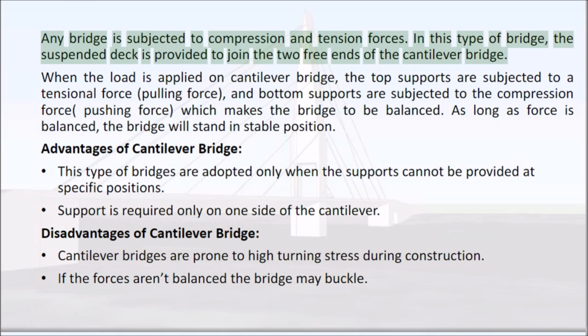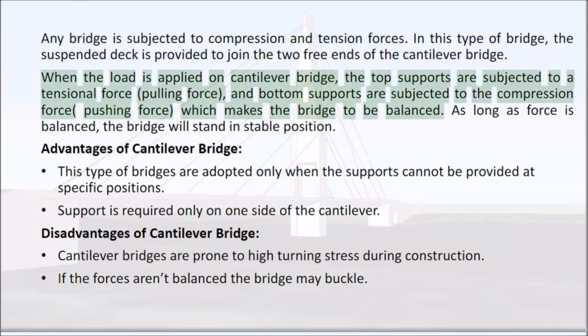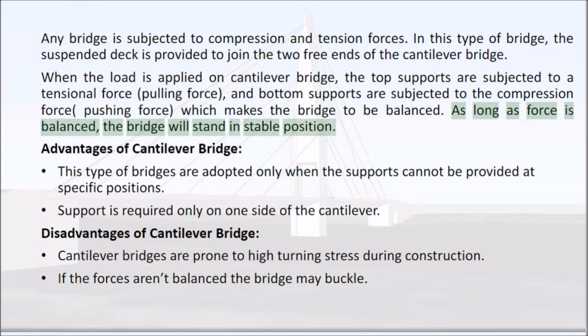Any bridge is subjected to compression and tension forces. In this type of bridge, the suspended deck is provided to join the two free ends of the cantilever bridge. When the load is applied on a cantilever bridge, the top supports are subjected to a tensional force, pulling force, and bottom supports are subjected to the compression force, pushing force, which makes the bridge balanced. As long as force is balanced, the bridge will stand in a stable position.